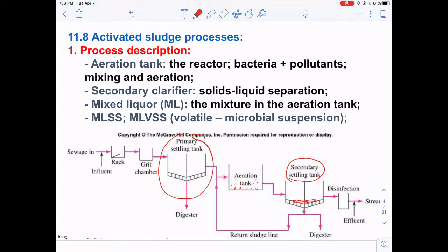And this activated sludge can be introduced back into the aeration tank, to basically enhance the concentration of the microorganisms. So as we have mentioned, the bacteria existing in the wastewater are the bacteria just existing in nature, right? So by bumping up the concentration of these microorganisms, we're simulating the natural processes, but we're trying to process the water with a faster speed. And because of that, we need to bubble a lot of air inside, because the oxidation of the BOD or oxidation of these organics is going to require a lot of oxygen.